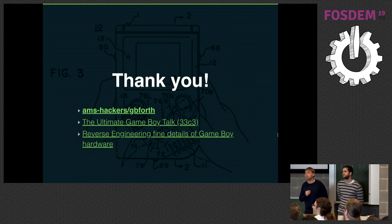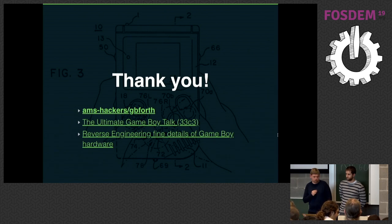Simple question: what do you use to test on the Game Boy? Do you have special programs? So the question is how we test ROMs. There are indeed special cartridges that use SD cards to load the ROM. They have a little OS built in as a file manager, or you can use cartridge flashers. You can buy them online for more persistent flashing.